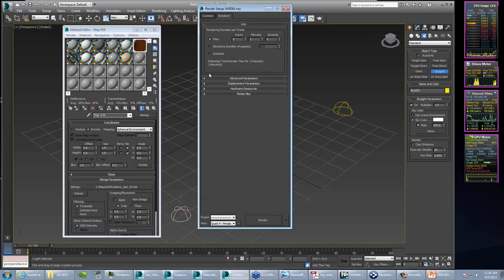So, very, very simple settings. You've really only got 3 settings that you generally need to worry about as far as the quality of the image that you're going to produce. So the default is time, set to 1 minute. We never really use time unless we have a deadline that we're trying to hit. This is a great feature if you know you need to be done by noon and you've got to get that image out, and you got 60 minutes, and it'll just run until 60 minutes and then save your image out. So under those circumstances, or you just want to do a quick thing and you don't care about the overall quality, send it out with 1 minute or whatever.